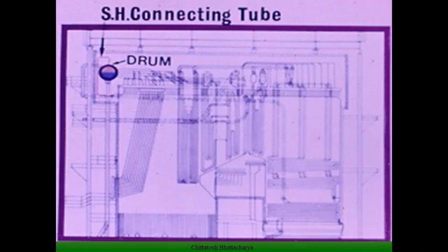It is done so that there is fine tuning of the steam temperature control, and the temperature difference between the steam and the tube metal temperature can be kept at a minimum level. So this way we monitor and control the superheating.